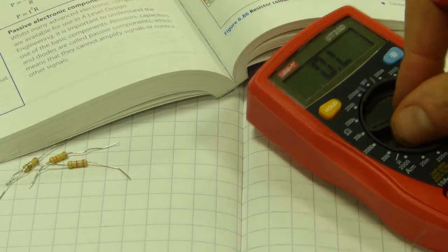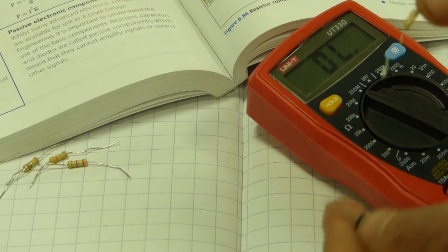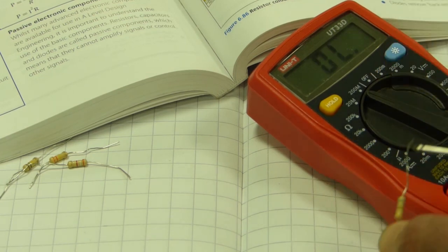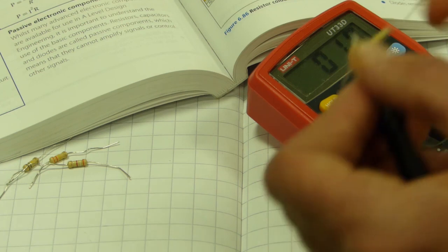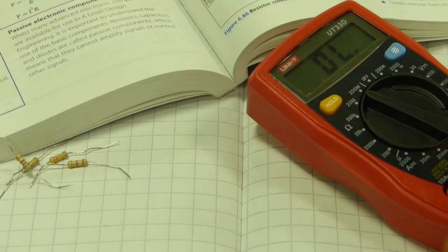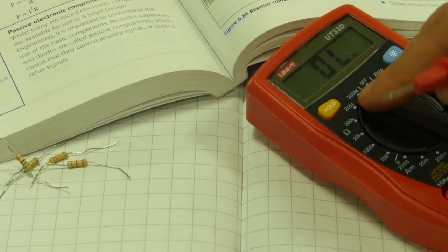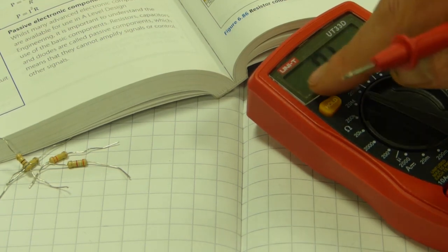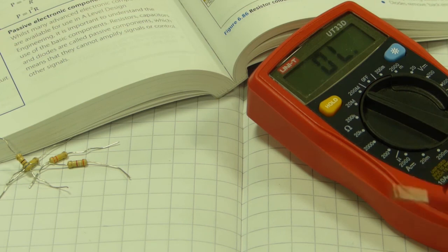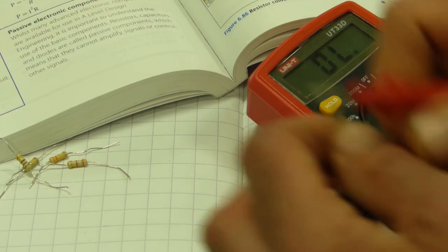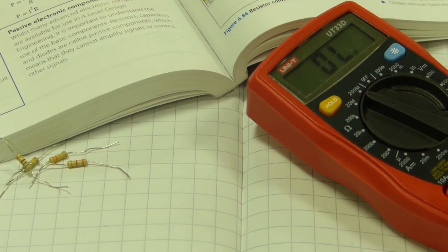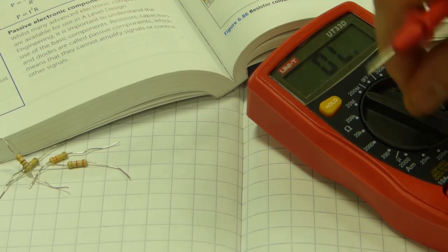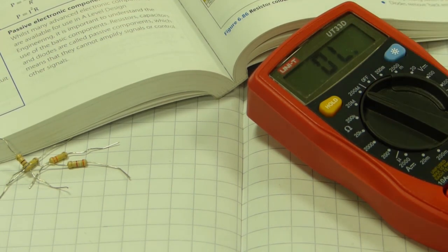If you're starting off on a big range like that and you get a smaller resistor, let's say this one here. Again, I'm still not picking up that small resistors, but let's say if you had a 300 ohm resistor and you're up in a 200 mega ohm range, it's just going to come out 0.00. It's going to think it's a total conductor there, so you've got to turn it right down, work your way down until you get a decent range.